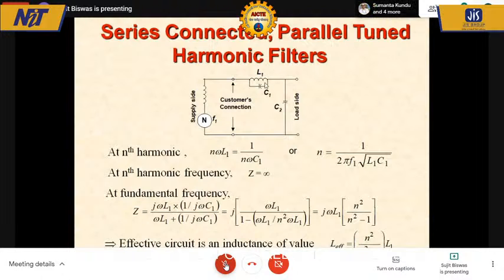The problem with this is, for one harmonic, yes, it's good, but usually we have multiple harmonics that we have to filter out. Fifth, seventh, etc. So you have to add in series different tuned filters. So one filter for the fifth, another in series for the seventh, and so on. As a result, you have different values of inductors in series, and for the fundamental current, you have a large reactive drop in series. So the voltage on the load side will start reducing because of the large reactive drop due to fundamental alone, because at fundamental it behaves like an inductor. That is one of the disadvantages of this type of filter.